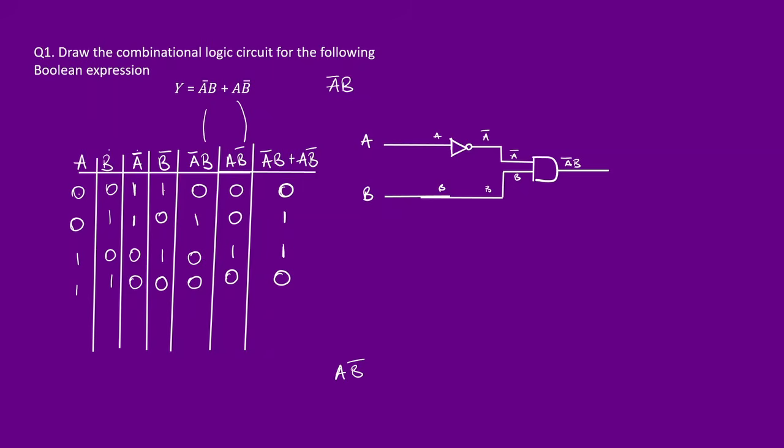So now we have to design A not B. You've got the A line over here, but we don't have anything to do with B. So what I would do in this situation is to bring out A. Draw it out. Bring out B. Draw it out. So that I have space to work properly for my expression. So recall, you have to be very careful now. This is A and this is B. But the term we need to make is A not B. Meaning we need our NOT gate. We need our inverter.